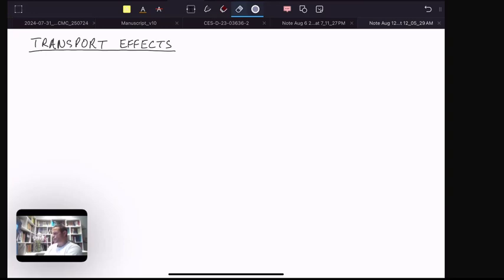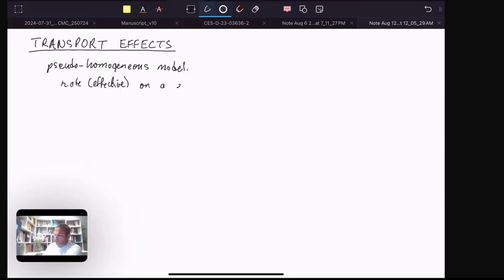We will learn to answer all of these questions, and along the way, we will construct pseudo-homogeneous models for reactions and transport processes in packed beds and porous media. We still describe the rate on an events per volume per time basis, even though the actual reactions may be happening at active sites at some dispersion, the number of sites per area, and we're in a catalyst with an amount of area per gram, and the catalyst has a density, mass per volume.